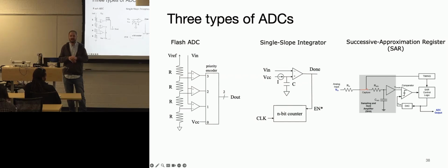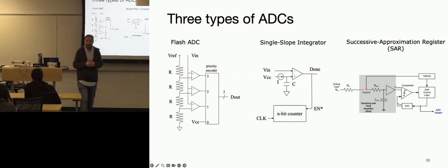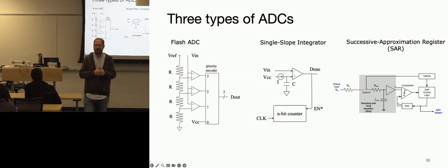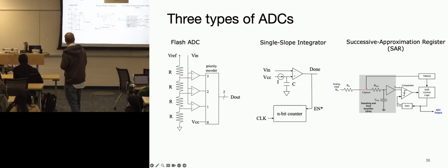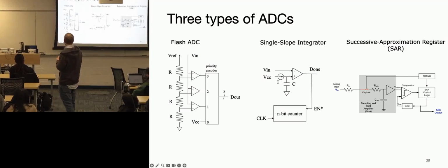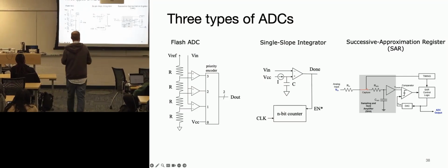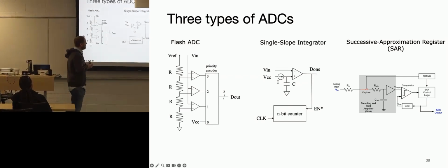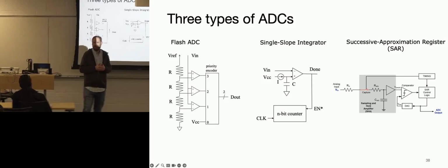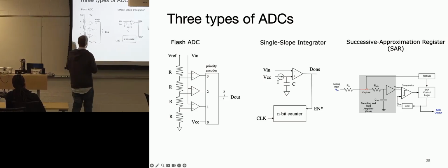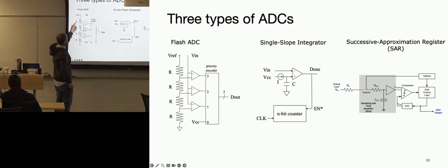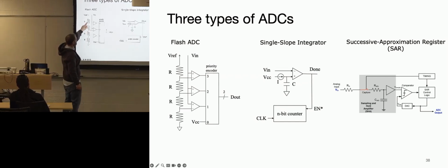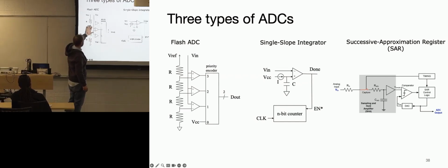All right, any other ADC questions? Or DAC questions? On the exam, would we just need to know that it's a flash ADC versus the others when we're doing the problems? Yeah, that seems pretty reasonable. If I looked at these three, I'd say, here's this voltage ladder, and if you understand the voltage ladder and that at every node you're making a decision, you don't really have to know how the priority encoder works.